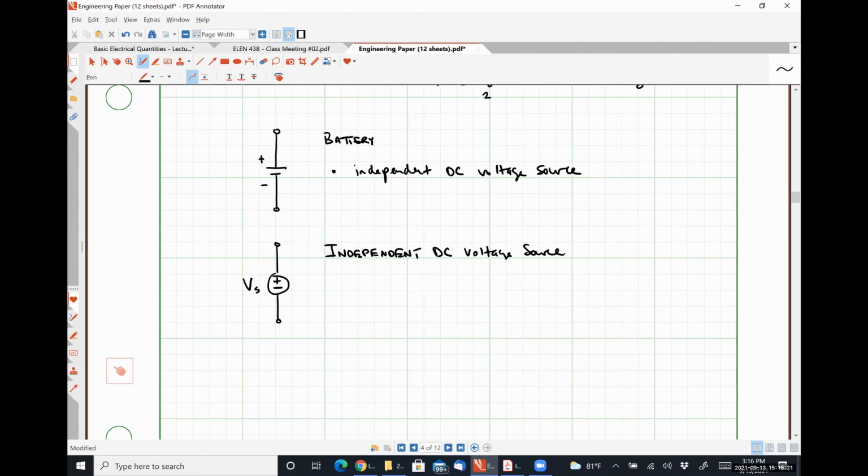So if the batteries were ideal, that short circuit would cause an infinite amount of current to flow out of that battery pack, right? Because our batteries are not ideal, there's a fixed amount of current that could possibly flow, what's known as the short circuit current. So we're causing a short circuit fault. And for a AA battery, that's somewhere on the order of a couple of amps to maybe tens of amperes, okay? So it's not a whole heck of a lot, but it is enough to cause those batteries to heat up so much that they will absolutely melt that plastic.